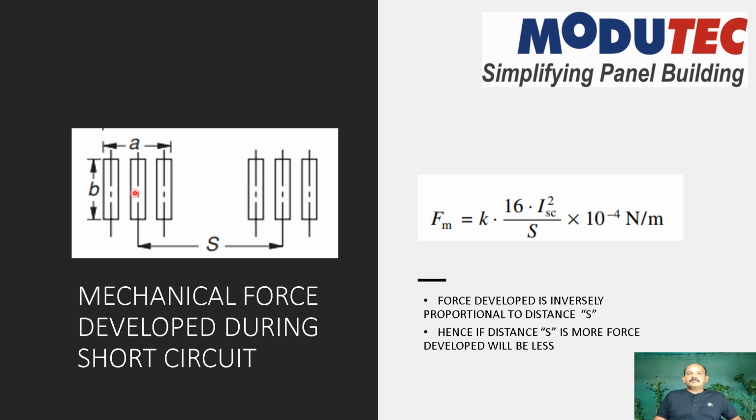Maximum we can go based on our space availability. If you increase it here, it will not change major results in the bus bar current carrying or short circuit. We always have to ensure that the phase to phase distance matters in design.